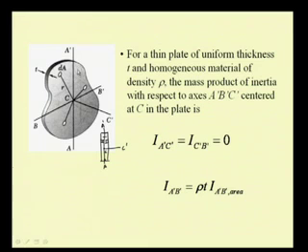And the product of inertia of this mass element in the plane A prime B prime is equal to rho T times the product of inertia of the area, that is I A prime B prime area. So, now we see that for a thin plate we can determine all the quantities involved in the inertia tensor, those 9 elements of the tensor, by finding the area moments first and then finding the mass moments.